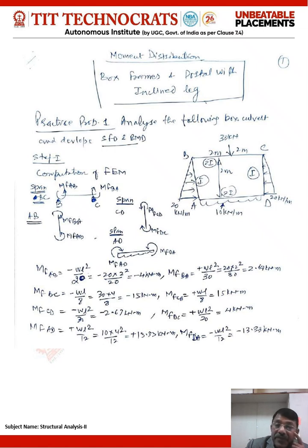Since B is at the top of the road, the distribution of load along the wall AB would be triangular in nature, as in the case of dams and retaining walls. Similarly, the loading for CD will also be the same, and upon the part AD, which is in contact with the earth, the earth's reaction of 10 kilonewton per meter would definitely be acting.